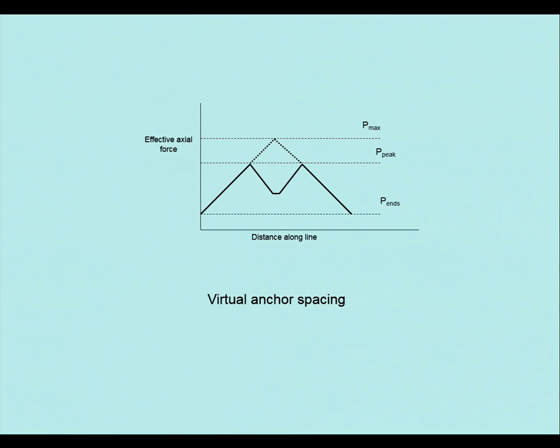So the other way of doing it, you make a note of, is we can lay the pipe in a progressive S, which you do anyway, because normally you lay the pipe, but the lay corridor is so small. But when you're doing S lay, you're snaking it out quite a few hundred metres either side. But the one disadvantage of that is it's more pipe.